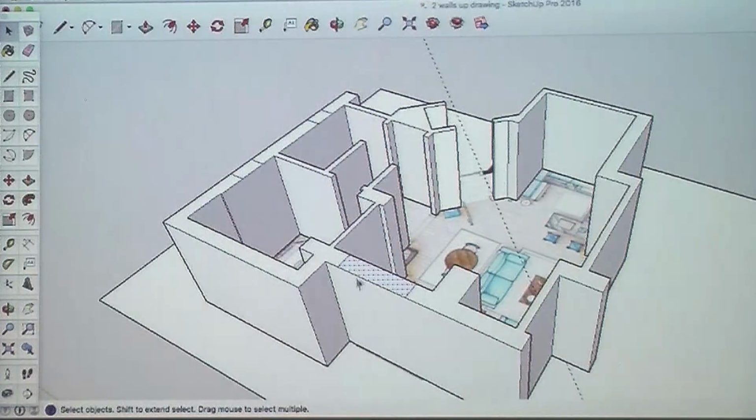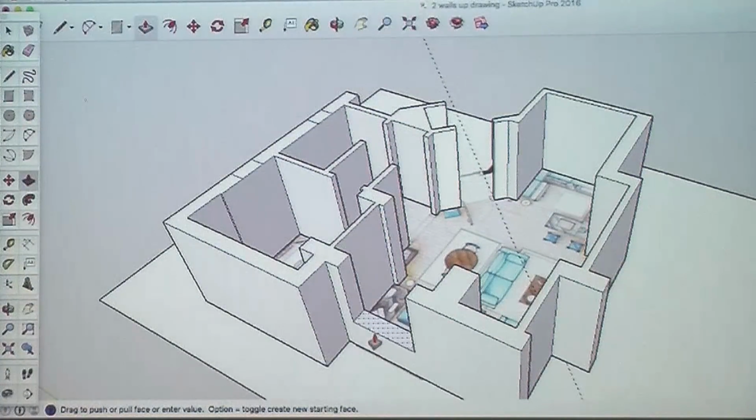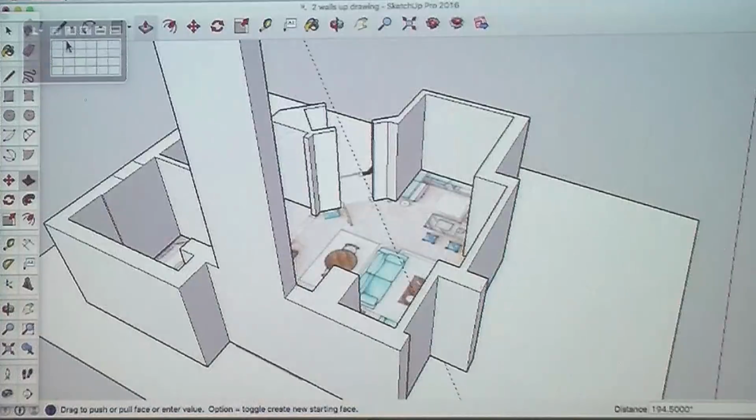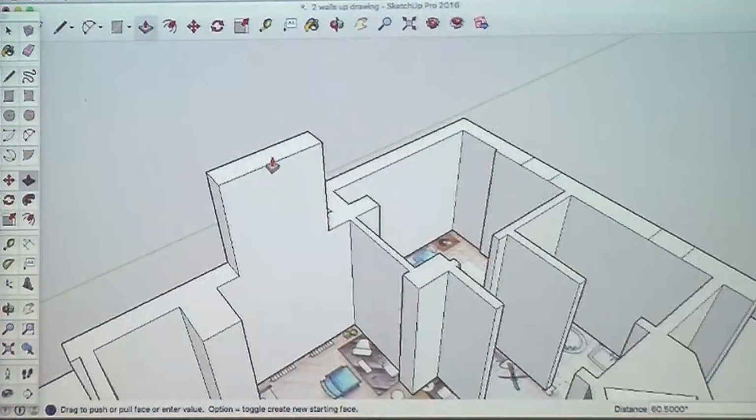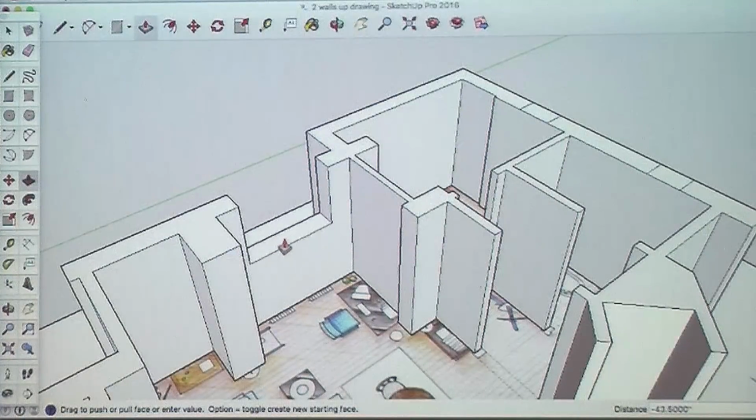So now that I put these rectangles in, I separated up this top face. So I have another face that I can push-pull. So I'm going to take my push-pull tool again, and push-pull these down, because I want to get the bottom of the window. Then we're going to fill in the top in the next step. So with push-pull, just so you guys can see this here, you can push-pull. Just turn this around. You can push-pull to a particular dimension.